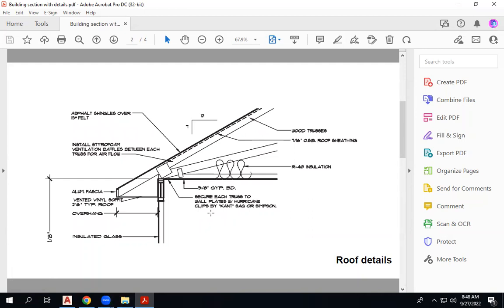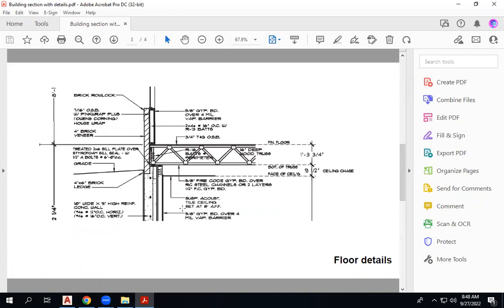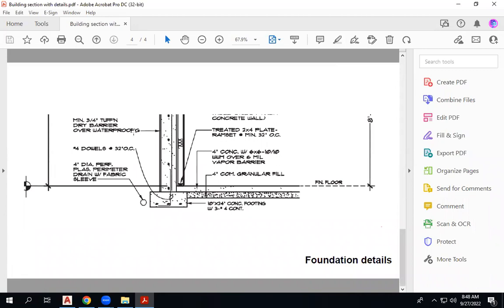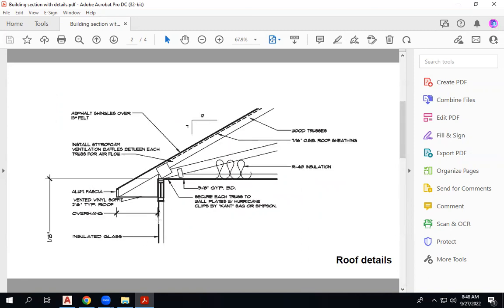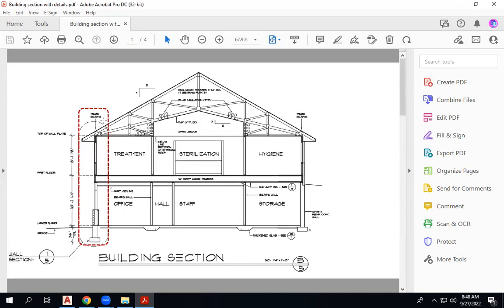So can you see now, if I connect these three also, you will get one wall section. This is the foundation, and this is the wall at the ground level, and this one here also, the same wall coming up, and then the floor, and then the upper floor wall, and also this will connect with the upper floor wall and the roof. So first we will try to draft the lines, and we will try to scale it first, because we need to have the drawing in the correct scale before we start anything.